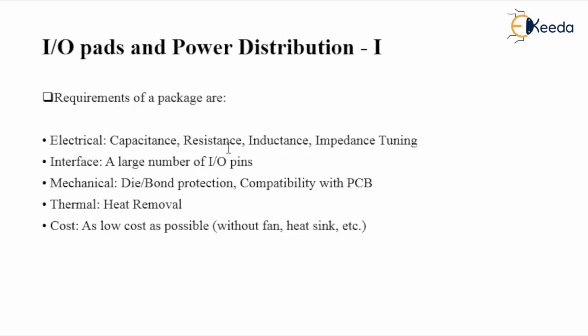Next, what are the requirements of this package? The requirements of the package are electrical, interface, mechanical, thermal, and cost. So these five are the requirements of this package. In the electrical requirements, we require capacitance, resistance, inductance, as well as impedance tuning.